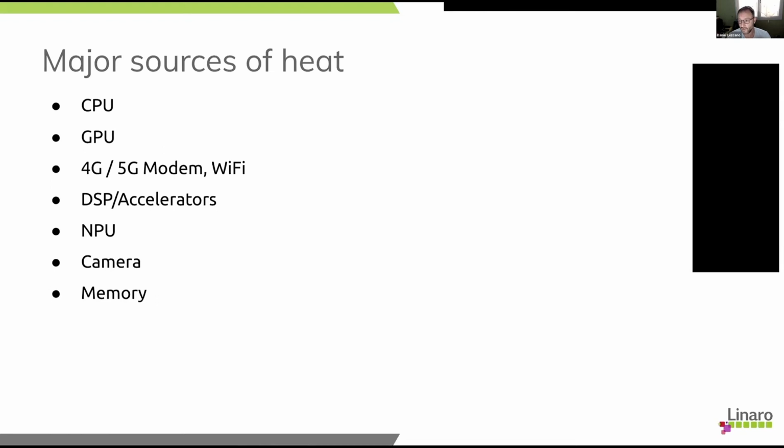We need something to prevent that, to mitigate, to have knowledge of how the platform behaves, and to say, okay, now I know that this kind of profile will use this device more than that device, so I will decrease the performance of this device instead of that device, and so on. With that, we ensure that we stay inside the power consumption that won't increase the temperature beyond this skin temperature.